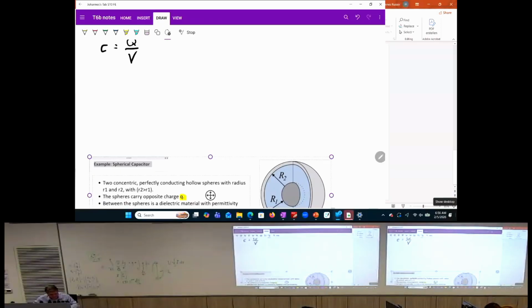First of all, it is important to remember not to mix up the letter C for the capacitance with the unit that we also have, C, which stands for Coulomb, which is ampere times second. The capacitance is a function of material parameters and geometry. Epsilon is basically the material, it includes the material properties, and then you have the geometrical properties.